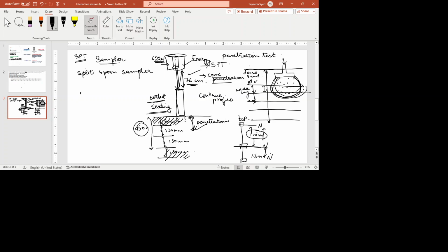The cone penetration test will give you the resistance to the penetration throughout the profile. So it will be a continuous function type thing. In SPT, we get discrete values. And another thing different from the cone penetration test is that we get a sample in this test. Because we are using this split spoon sampler, we actually get a sample at each SPT location. So that is about how and why we do the test.